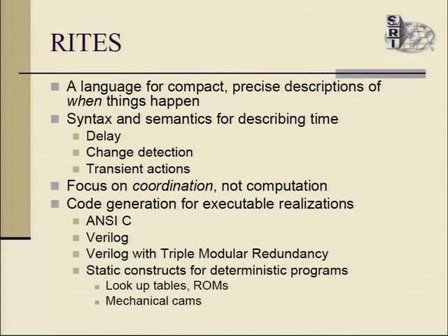Important for space applications, we also have code generators that produce Verilog with built-in triple modular redundancy. I'll talk a little bit more about that, but basically those are features to let the HDL work on non-radiation hardened devices in radiation environments where you might have transient errors. This helps protect the function against those kinds of things.